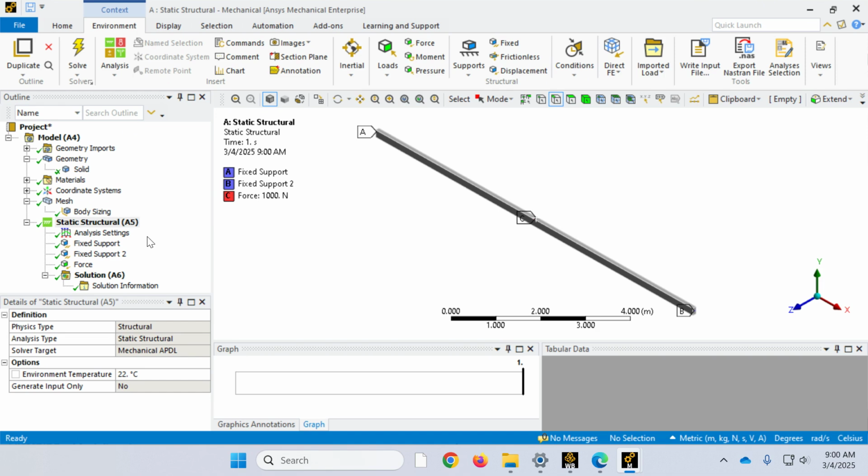Do I need to do any fixed rotation to prevent this from spinning? We do not, because we're applying the constraints to edges, not to a point. So this is not going to spin about its x-axis, like when we modeled the beam using a line concept. Okay.